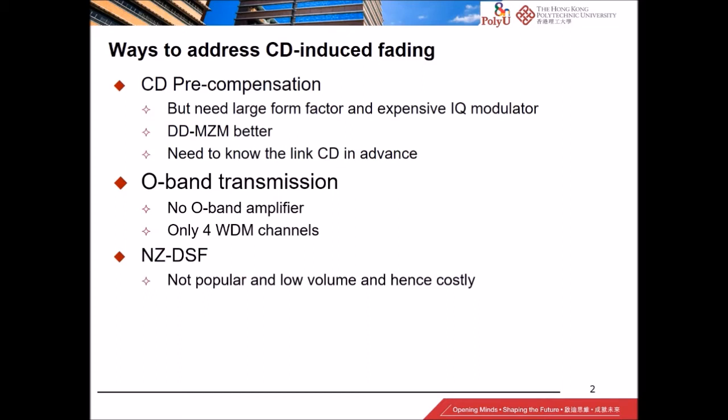Or you can use non-zero dispersion shifted fiber. Okay, so in principle, there's actually nothing in physics that prevents this approach from being useful. It's only that the production volume of NZDSF is rather low compared to standard single mode fiber. So that doesn't seem to be a very attractive option at this moment.